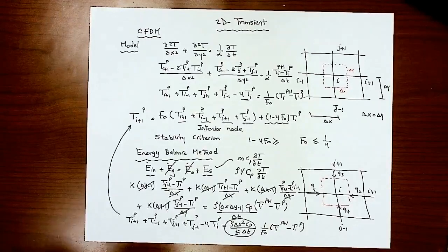Just to show you how to apply the transient finite difference method for different cases like interior node, node exposed to convection, and these exist in the table, but also I will include additional cases that are not in the table to show you how to use the energy balance method to get that nodal temperature. Then we solve steady and transient and compare the results.